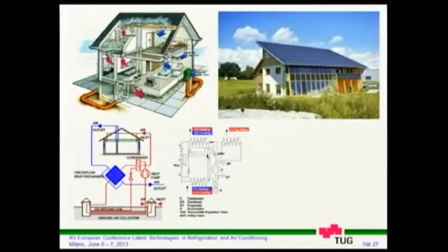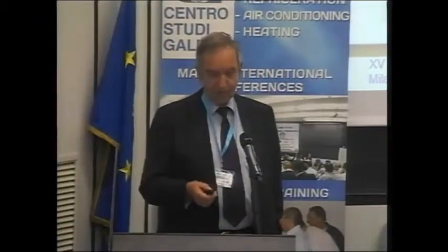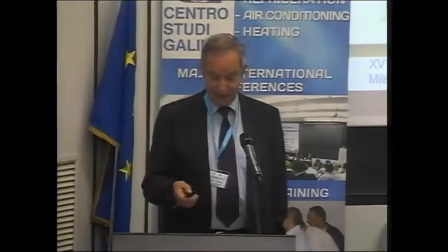A next step in this are the so-called passive houses, and in these so-called passive houses a lot of modification has been made. Strictly, you should not call them passive houses, you should call them ultra-low energy houses, because some of the rules of the passive houses are no longer valid. And in this case, you again have the possibility to combine a ground source heat pump with the ventilation system and to make a fresh air heating system. And the common value requested from the passive house producers is 15 kilowatt hours per square meter and year.